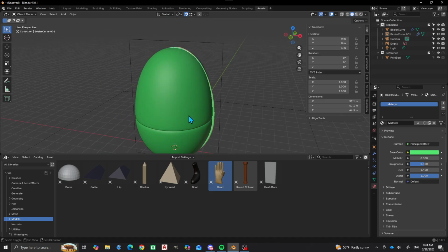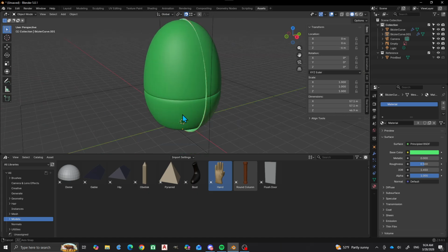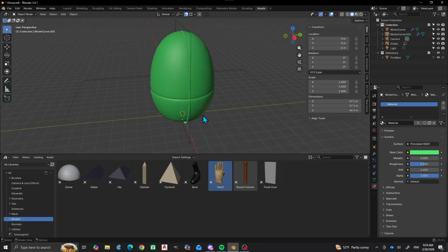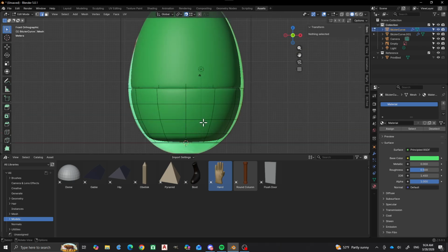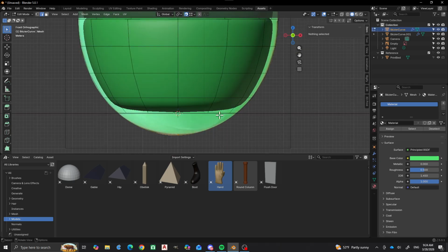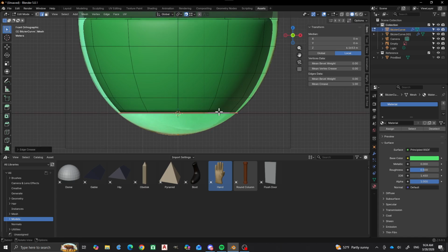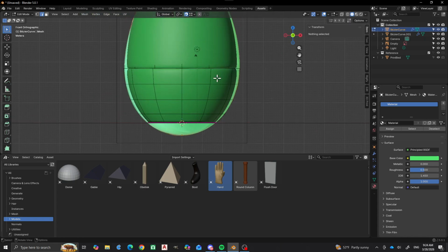And now we can take this so that we can export this to STL. So that's what we'll do, is that we are going to export this. I also want to make sure that this sits flat on the bed. So I want to do Shift E1. There we go.